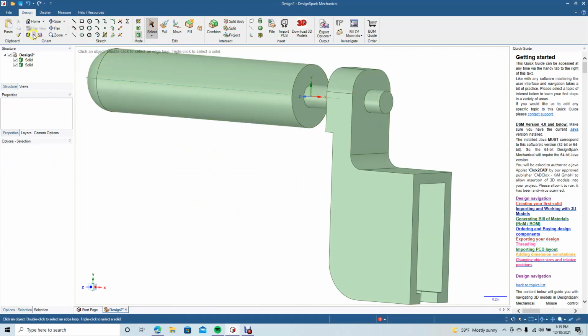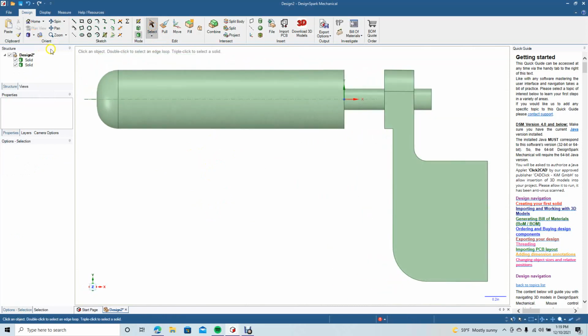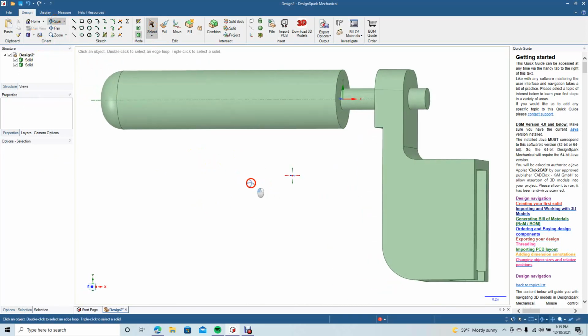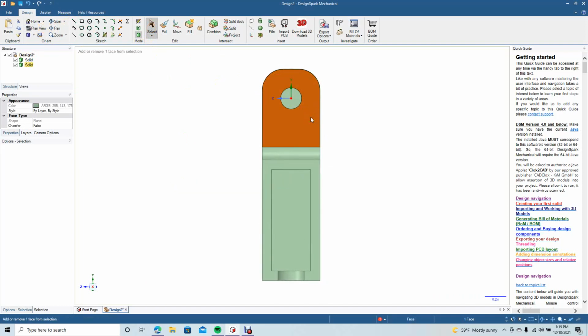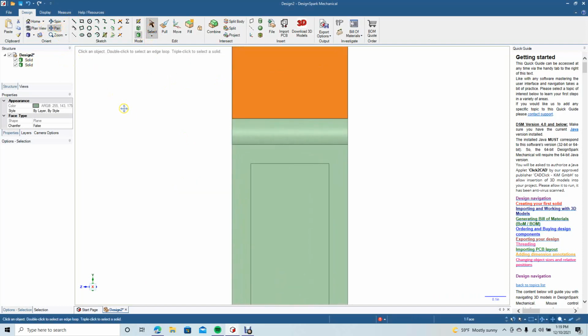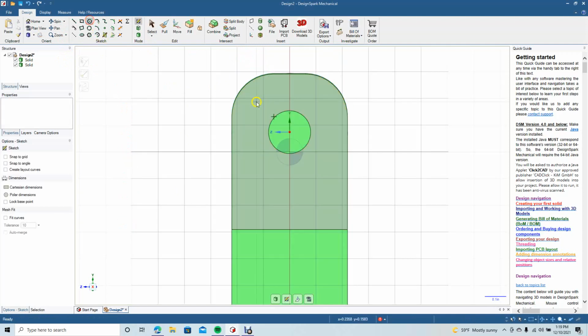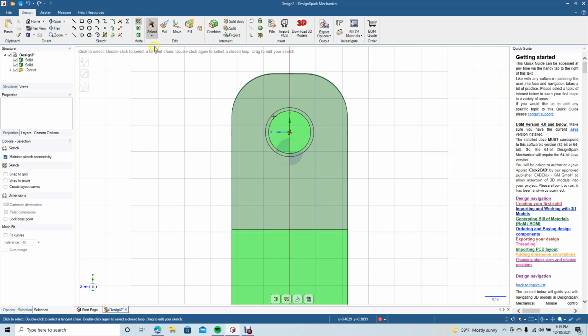All right, then we're going to go to top view. We're going to spin this around. We're going to click here, go to plan view. We're going to Control plus to zoom in. We're going to pan down. Now we need to make this hole here a little bit bigger than 0.2, so it has to be like 0.23. Okay, that's enough wiggle room there so the piece will rotate freely.